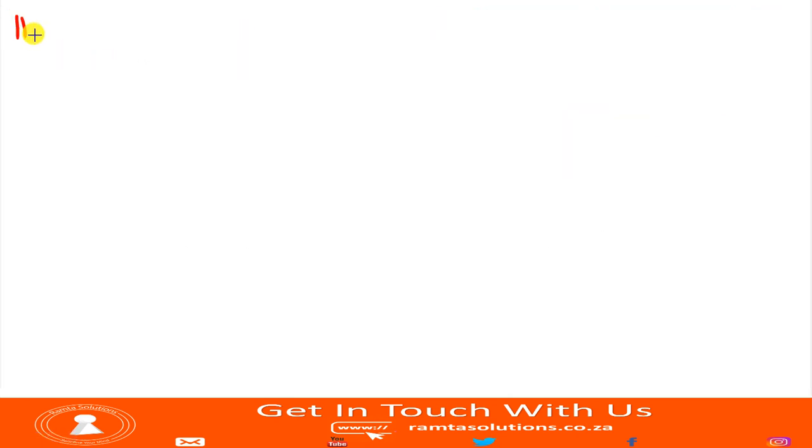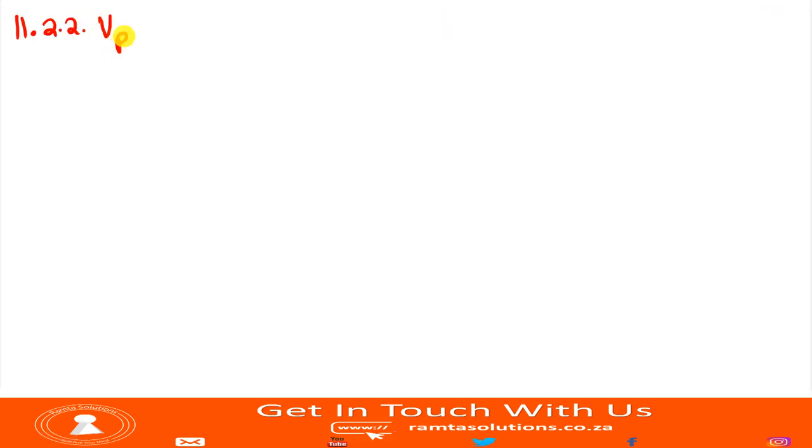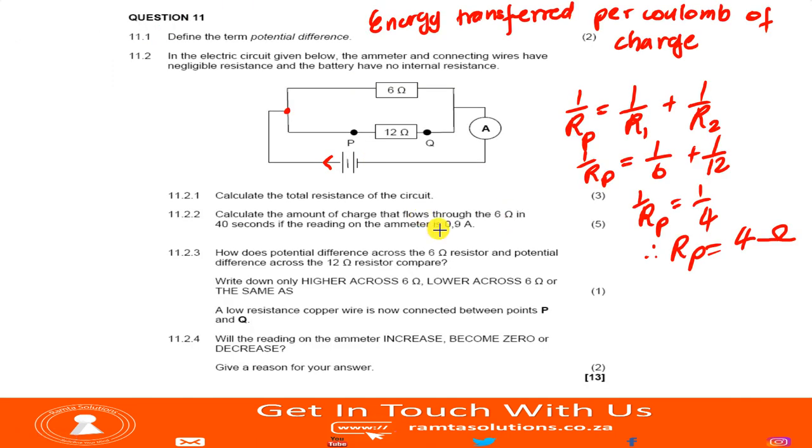11.2.2. Because this is a parallel connection, V parallel will be equal to V of each branch. We're looking for the charge, so we start by finding the current flowing in the 6 ohm resistor.